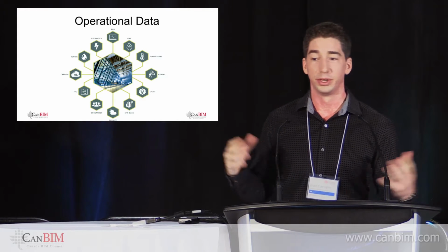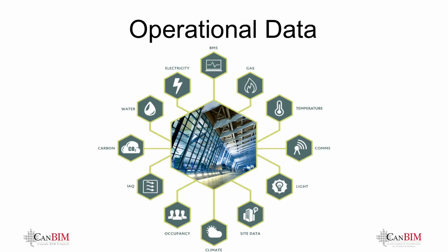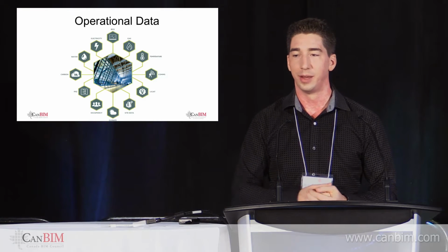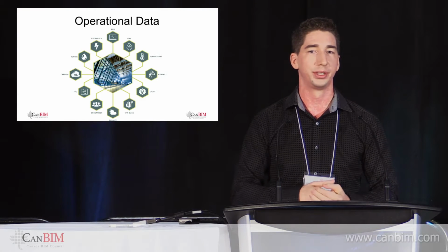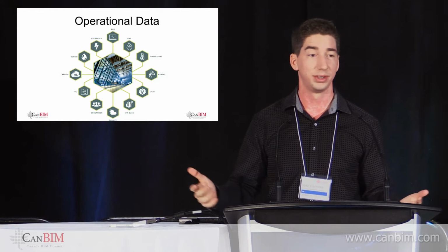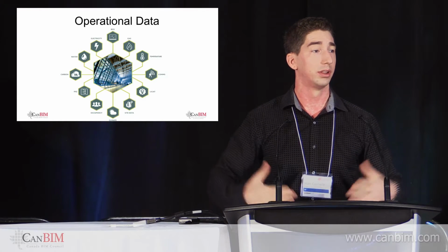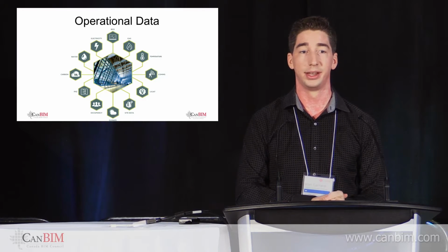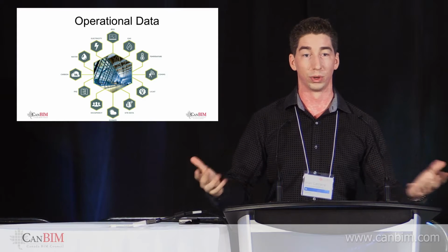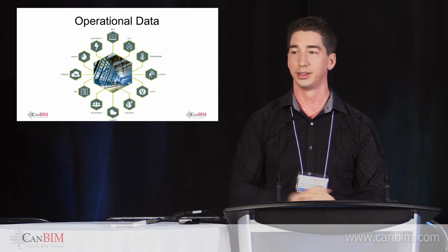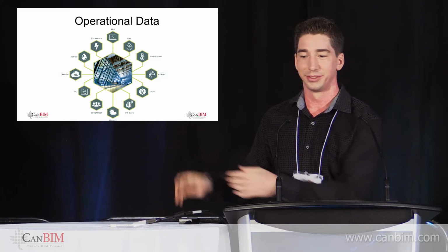So the operational data, what is it? How much of it do we have? We're talking about weather sensors, chiller performance, occupant sensors, you name it, whatever we can sense. Our typical building has 30, 40, maybe up to 100 sensors. That's a lot of information we're sensing, but we're just literally sensing it and putting it in a BMS and hoping that it just works itself out, hoping that your spec drawings were 100% accurate and that the environment will just suit itself.